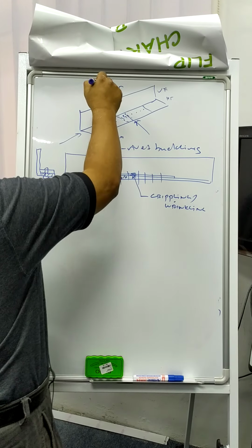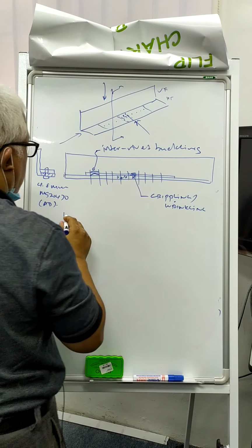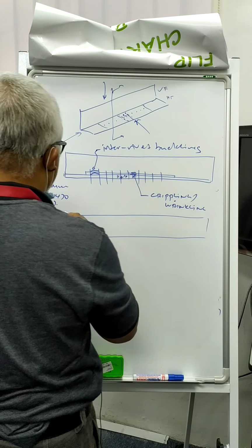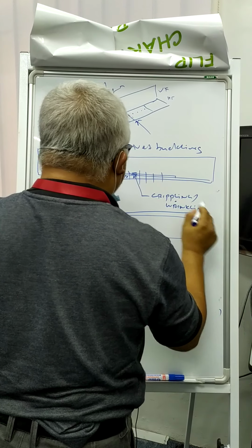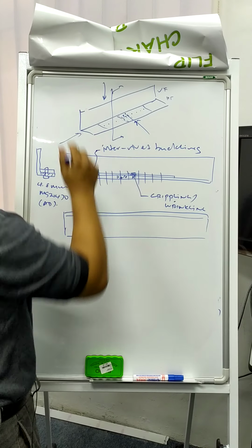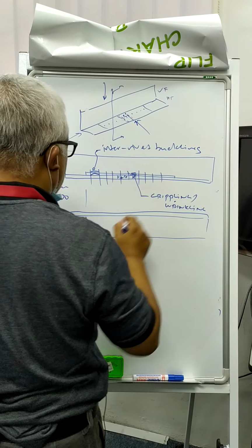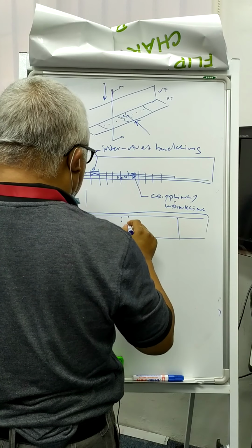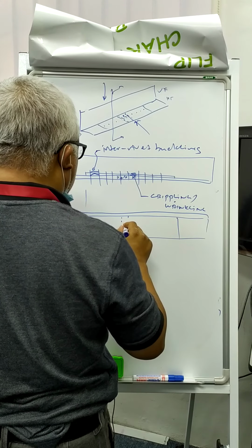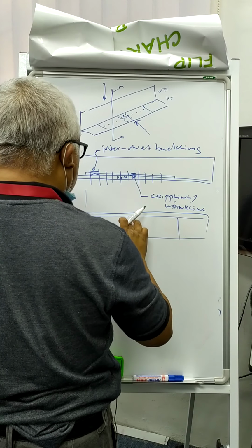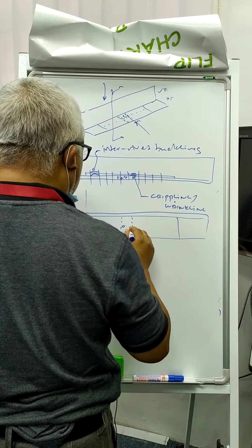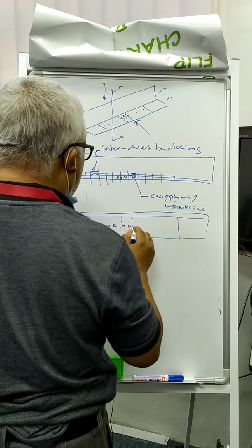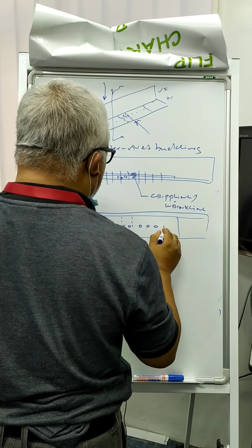And if you draw from this view, you will see the doubler. Okay, this is the flange from top view, and you have the doubler, we have the filler behind, 1, 2 fastener. 2 rivets, we have 1, 2, 3, 4, 1, 2, 3, 4 rivets.